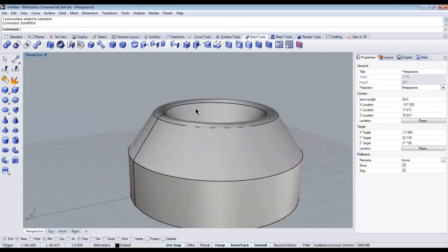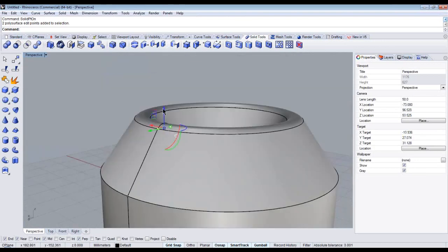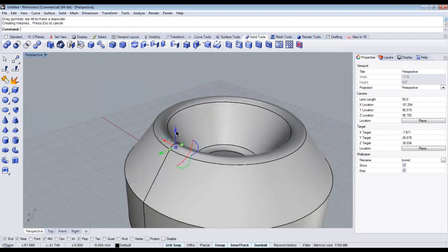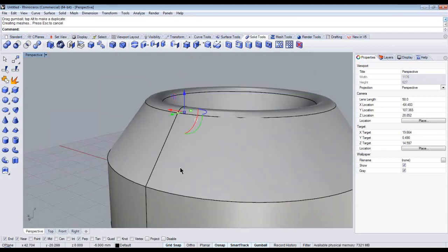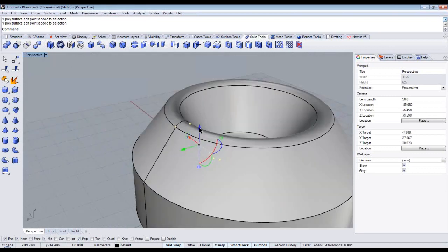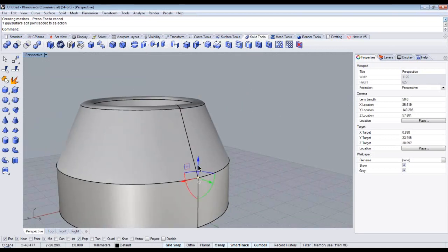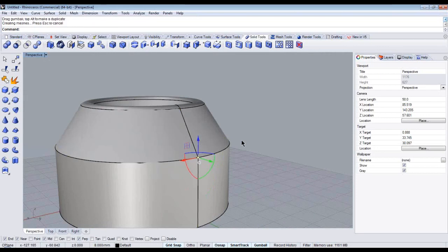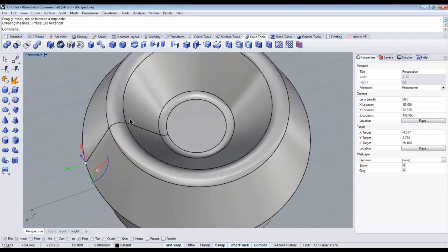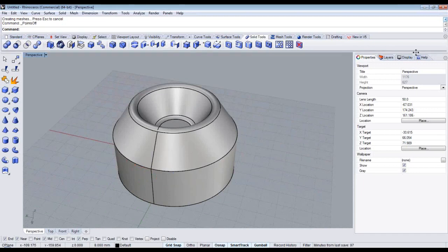Solid point on is a pretty big deal in that you can turn on control points for polysurfaces. And those control points can then be moved. And you'll notice that I'll keep the fillet intact with that translation. And if I select just that one, I just move that whole edge at once. So you'll find these solid points at the intersections of surfaces within the polysurface. And F11 turns those off.